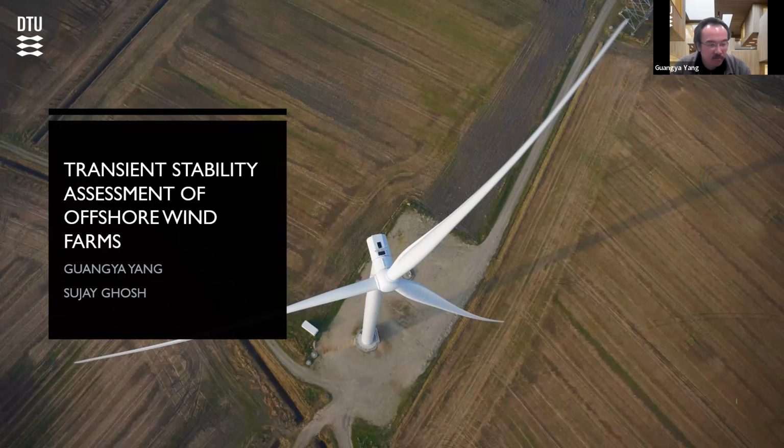3 years ago or 2.5 years ago, where Suji, my PhD student, and I together developed the methodology to look at the transient stability of the wind farm, typically from a grid-connected converter perspective. So this presentation is mainly on one piece of the work that we did, looking at the region of attraction for the grid-connected converter, and extending the energy function-based analysis from a static energy function to a time-dependent energy function.